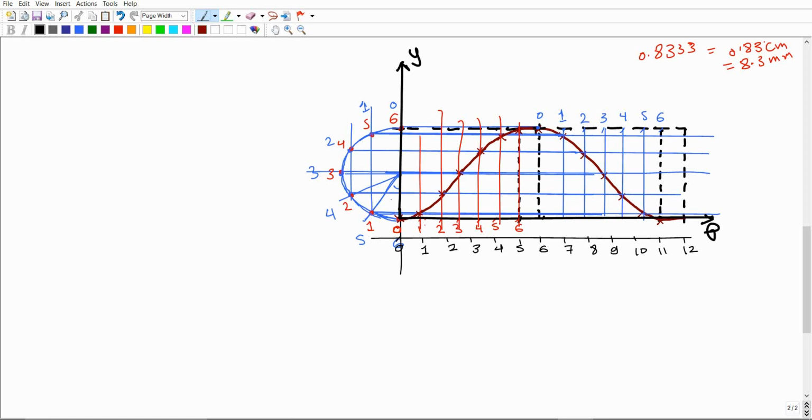So I'm just going to draw another vertical line. You can use the arrow triangle to draw this vertical line with an offset distance in this way. This definitely is going to give us the center axis of the cam, and the center of rotation of the cam should be located somewhere over this line. Make sense? So this is the second step.